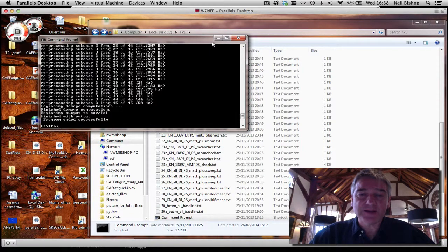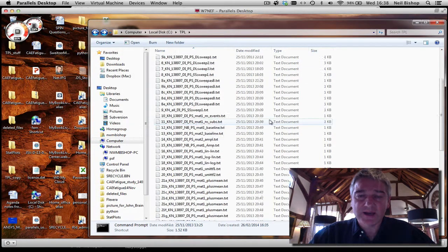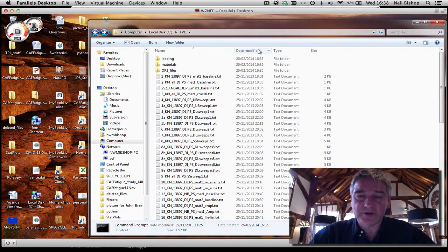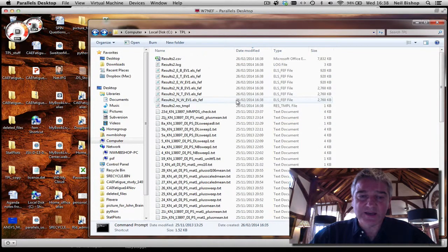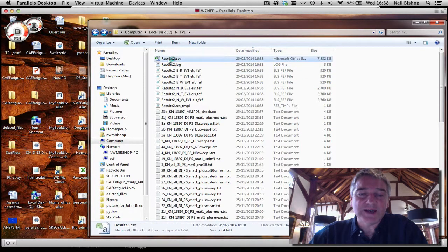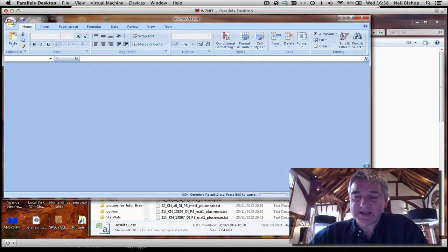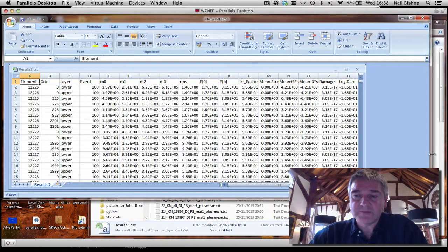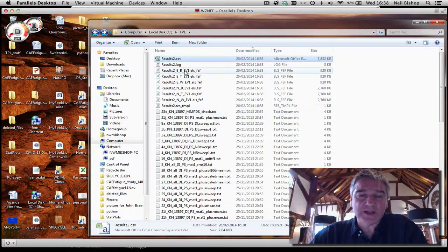So if I now go back to my directory, and if I sort based on date, I should see all the files I've just created. So I've created a set of results files in FEF format, and I've created a CSV file here, which can be opened with Excel. If I just open that up now, I've got an Excel file with all the results included. And the FEF files can be imported into Patran. I won't do that now, that will be the subject of another video.